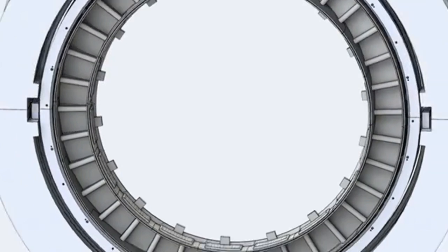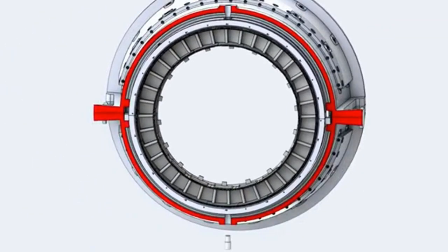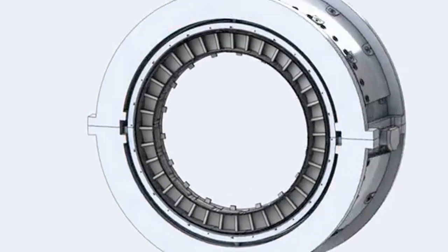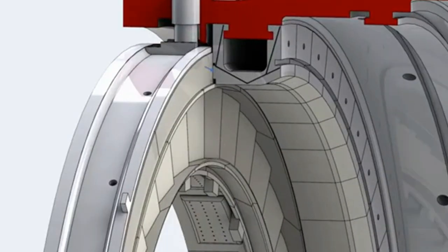The retaining ring is centered by 2 eccentric pins from the turbine shell. This configuration permits radial expansion due to the high temperatures encountered, while the ring remains centered to the shell. The aft outer face of the retaining ring is loaded against the forward face of the first stage shroud, with seal strips in between to prevent compressor discharge air leakage between the nozzle and the shell.